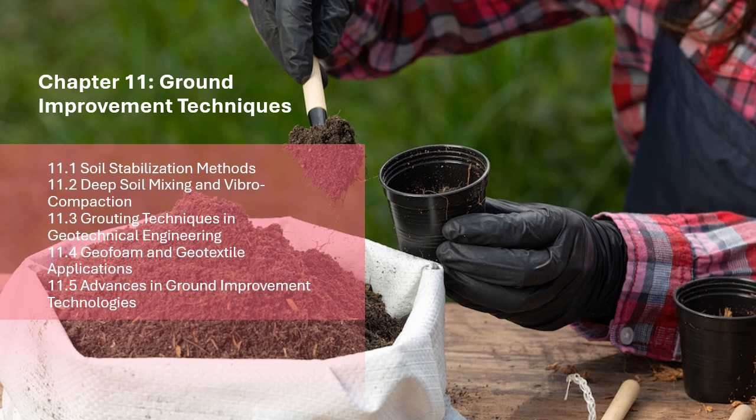1.3.5 Limitations of grouting. Soil characteristics. Grouting may not be effective in soils with very large voids, highly fractured rock, or highly permeable materials, where grout may not adequately fill all gaps. Cost variability. While generally cost-effective, the cost of grouting can vary depending on the depth of injection, type of grout used, and site conditions.